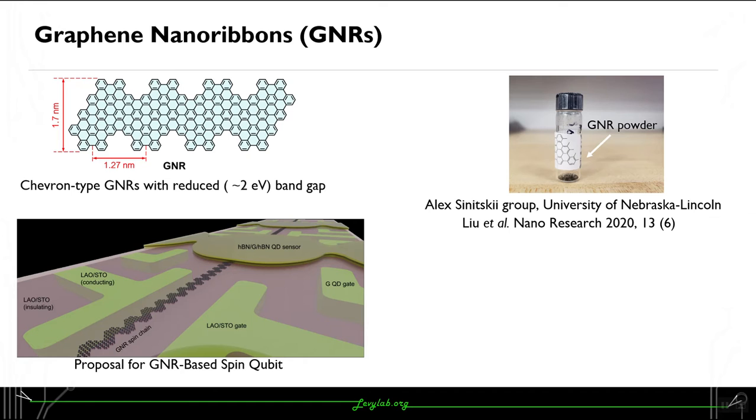Graphene nanoribbons, or GNRs, emerge as a promising electronic material with many interesting electronic properties, including topological quantum states and a highly tunable energy band gap that depends on the structural design of the GNR and can be controlled during the chemical synthesis. GNRs have recently been proposed as a promising candidate to host a new family of spin qubits. A big milestone in reaching this goal is to be able to have direct electrical contact and apply gate voltages to individual GNRs. We can apply a transverse electric field to a metallic GNR that will open an energy band gap, leading to the formation of a topologically protected electron state.